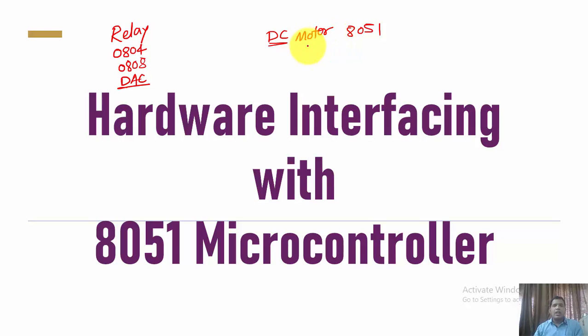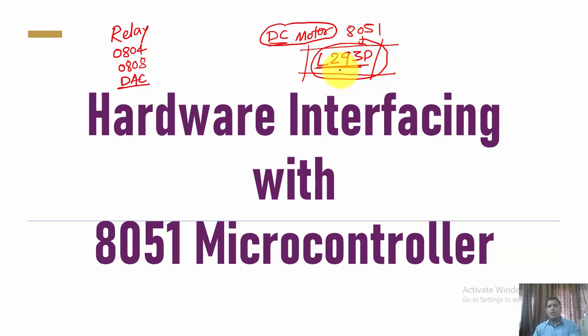microcontroller. In order to interface the DC motor with the 8051 microcontroller, we rely on a motor driver IC, known as L293D. So we are going to discuss the logic to interface the DC motor with the 8051 microcontroller through this motor driver IC, that is L293D.